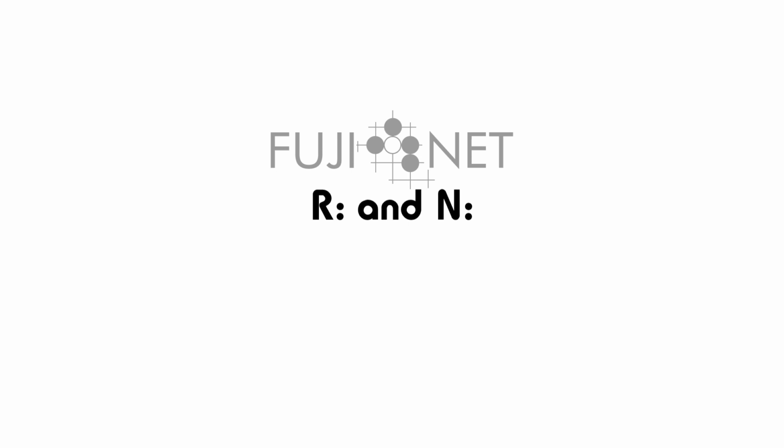The N device is actually a new device providing network card function, offloading a wide variety of protocols using the processing power of the ESP32, and as a consequence, exposing a clean I/O interface to the Atari and making it really easy to make a whole new class of networking applications for the Atari 8-bit.